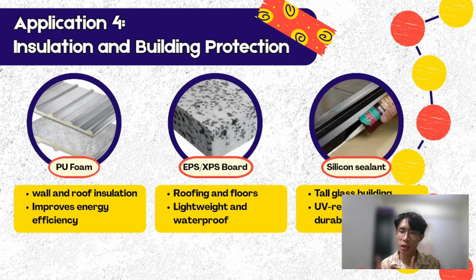PU foam and EPS board are mainly used in roofs because they are lightweight and waterproof, and PU foam improves energy efficiency. And silicone sealant is mainly used in tall glass buildings, as I mentioned before, because it is UV resistant and durable.